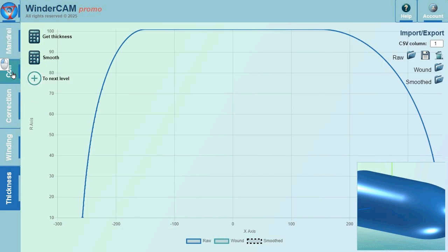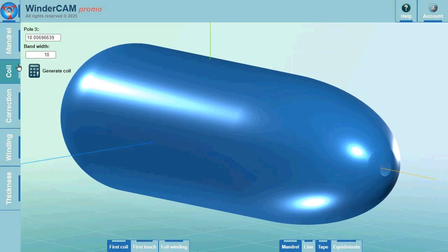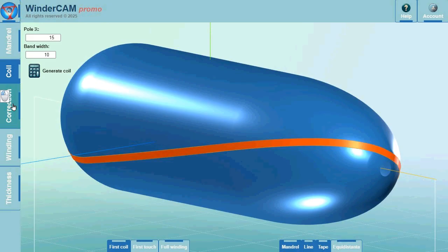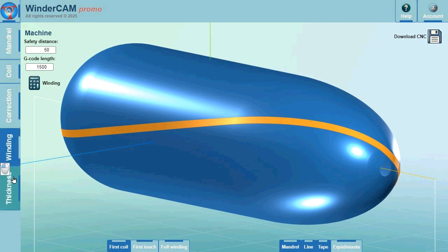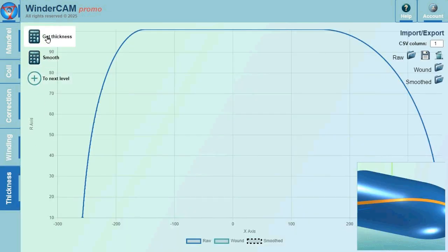After each calculation, the site again determines the actual thickness of the accumulated layer and the updated outer profile of the shell. At each step, the outer profile is smoothed out, so that by the end of the calculation, we get a realistic multi-layer structure that can be implemented without any jumps. As a result, the engineer sees the finished model of the wound product, knows the thickness distribution along the length, and receives ready-made trajectories and a control program for the actual machine.